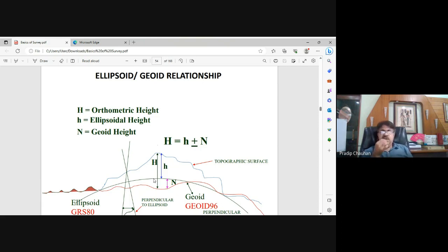So most of the rivers, if you see, the very old river will be at a slope of 1:3,000 to 3,500. And if it is a too young river or in hilly terrain, you might find 1:1,000, 1:1,500. Why is this important? Because if you are designing a bridge, you need to work out the highest discharge. Or if you are designing certain canals, discharging systems or some river training work, all these levels are important.